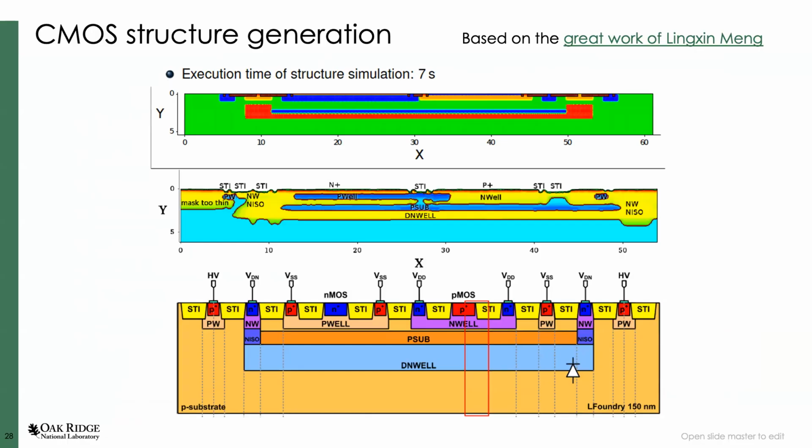Yeah, that was a bit of that. My first approach was, okay, if we have all the process, it can be better than that, right? And I still think it's the case, but with infinite computing power. So that's mainly what we learned from that: the foundry, they care more about their thermal. For example, they do quite detailed simulation of the thermal history of the wafer, which is done in simulation at great length. So out of the 43 hours, you spent maybe 30 hours doing thermal simulation. We didn't need that plus or minus 100 nanometer level of detail for these big implants and such.